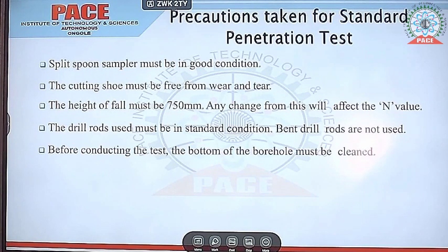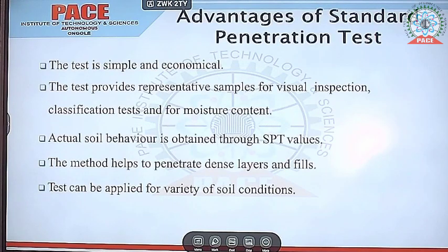The main advantages of this standard penetration test: mainly this test is simple and economical. The test provides representative samples for visual inspection, classification tests, and for moisture content. The actual soil behavior is obtained through SPT values. The method helps to penetrate dense layers and fills, and this test can be applied for a variety of soil conditions. These are the main advantages.